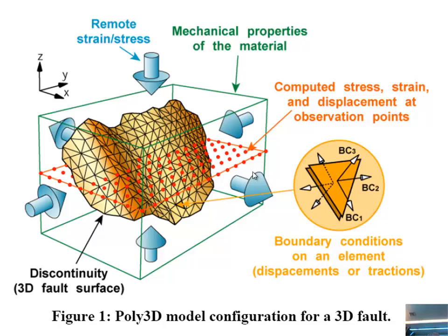I can have two rectangles to do this, but if I have something up here, I'll have a gap. Whereas triangles let us do a completely closed surface. But it's not a big problem unless you're very close to the fault. The gaps don't matter, so that's why the rectangles of Coulomb are okay. But if you look very close, you'll see these holes, and this can be a problem for complex faults. That's why these guys did Poly 3D.